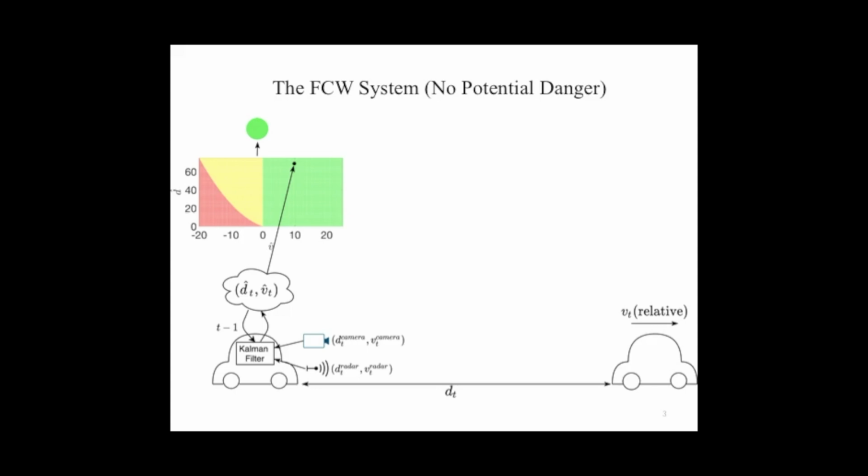I would like to mention another important aspect about the Kalman filter, which is characterized by the loop between the thinking bubble and the Kalman filter rectangle in this plot. This loop of double arrow means that the Kalman filter is a sequential system, and it performs state estimation by smoothing the state estimation in the previous time step, which is t-1 here, and the current measurement at time t. This also implies the state estimation we obtained so far intrinsically depends on all historical measurements. And we will revisit this when we talk about the attacks.